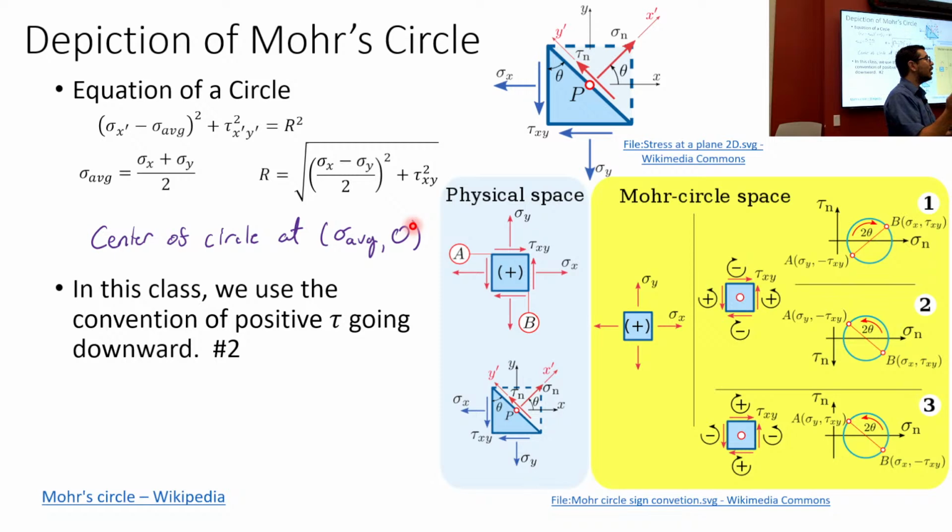Folks? Counterclockwise or clockwise? Theta, the way we've been defining it. Someone? Anyone? Yeah, it's counterclockwise, okay, right? Now, with Mohr's circle, if you define it this way and you use our current conventions for what is positive, if we put the tau in, a counterclockwise rotation of the element corresponds to counterclockwise rotation on Mohr's circle. Okay? So that's why we use this convention with our other conventions.